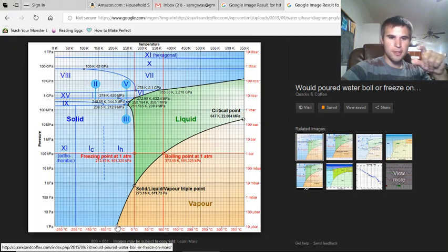So if so many BTUs per second were enough to have raised the temperature up to the boiling point, or in this case the sublimation point, we need, I forget what it is, but there's an exponentially larger number of BTUs that are needed to actually jump us to that last degree and actually phase change. So by increasing the heat in the entire system, we make sure that there's ample energy, ample BTUs available to all of the solid food, all of the water molecules within the food, to encourage the phase change and to allow that to take place.